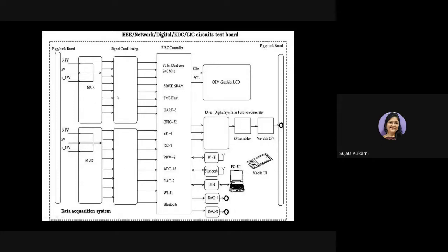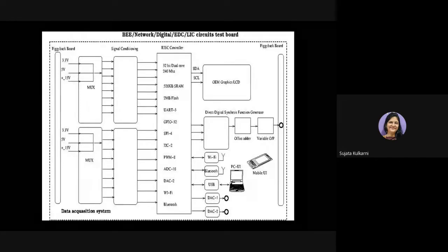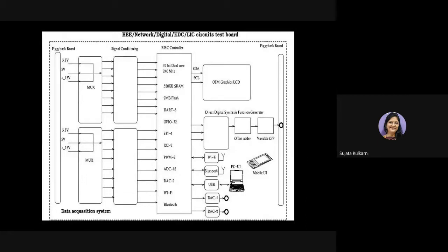All right, so that's the major challenge: since we have multiple subjects and multiple experiments, but the voltages are of different nature, we need to bring them to the acceptable form along with protection. Because at any point of time the voltage should not exceed 3.3 volts. So you should have protection on board, so that all the signals never ever cross 3.3 volts. There is a clipping, right? So you have to take care of that, and then you can give it to your CPU.